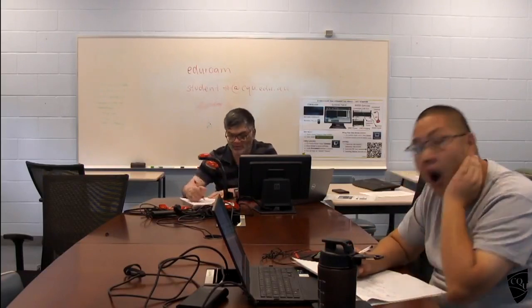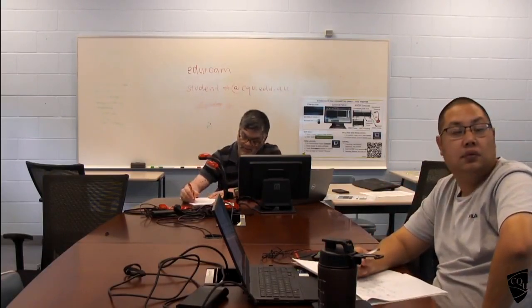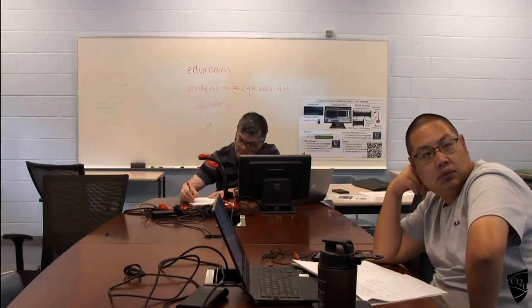So I need to find out the centroid of this whole area. If you look at that outline, it looks like this. So I need to find out the centroid. What I will do is divide this into two known areas: this one rectangle and the remaining area.